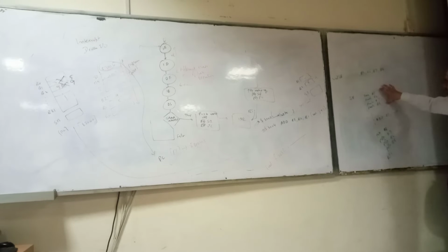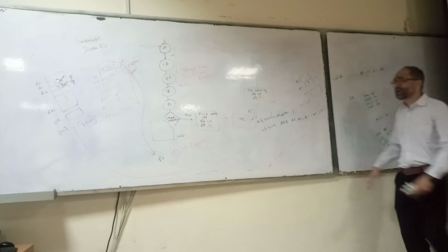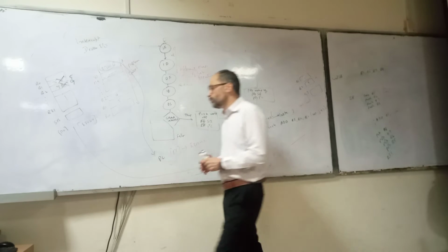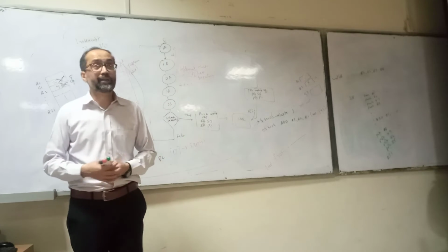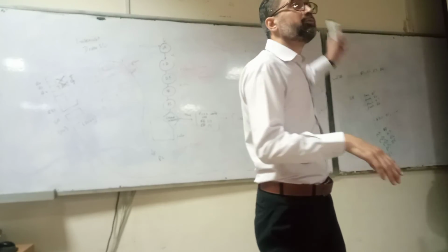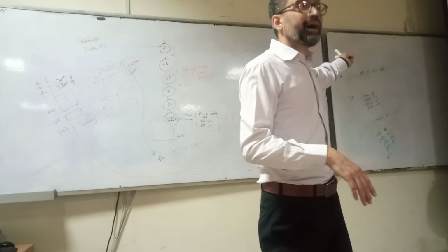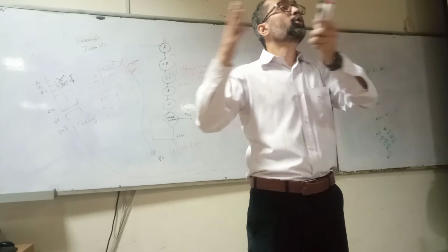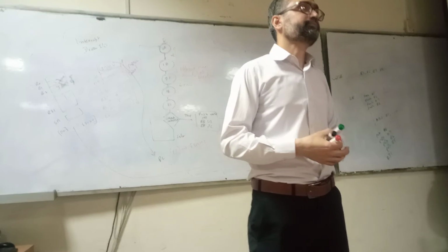Now, if you look at the switching time in this push and pop instruction, how many instructions are there? 4 plus 4, 8. So actually, first you need to push 4 registers and then pop 4 registers. Okay, which mechanism will be used? Either push all of the working registers, or only push those registers which are being modified by the ISR. It depends on the architecture.